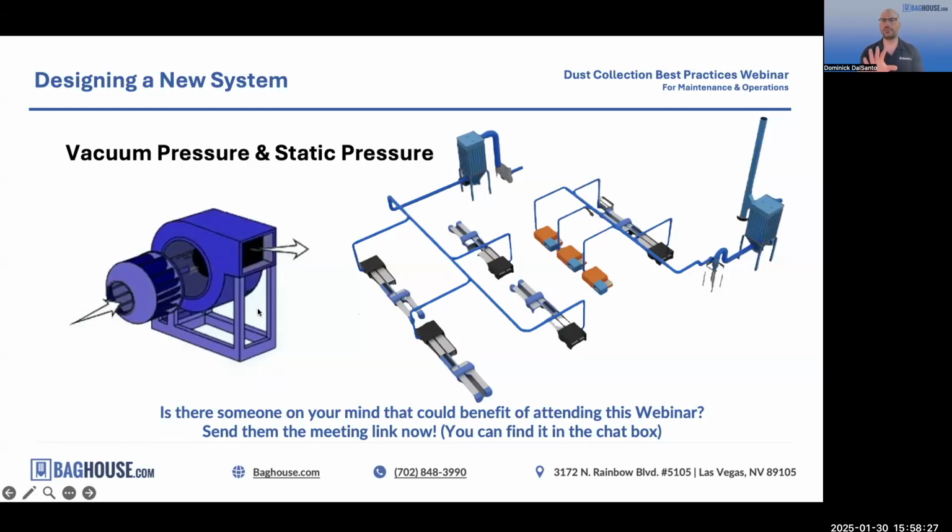Why does this matter when you're selecting the system? We're going to ask for quotes. Because when you size the fan, you need to know how much resistance you have to overcome to get the right size fan. Sometimes people think that this fan does 10,000 CFM, this one does 20, this one does 50. But actually, it's not just the airflow. If you read the full spec, it's 10,000 CFM at this static pressure, 10 inches of static pressure.